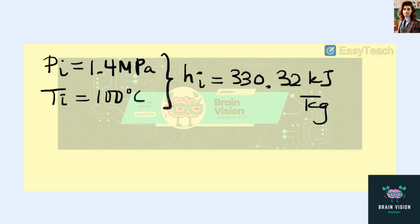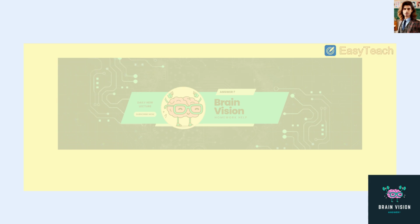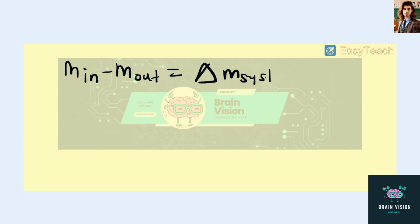What we're going to do now is define our system. We define the tank as our system and as a control volume. So we can write a mass balance and say that the mass coming in minus the mass coming out is equal to the change in mass of the system. As you know, there's actually no mass leaving. All we have is mass entering. So that's going to be mi is equal to m2 minus m1.